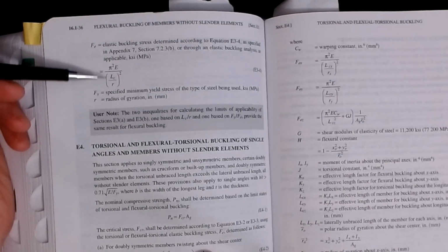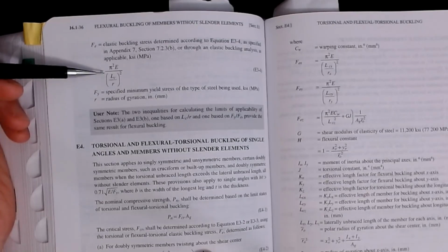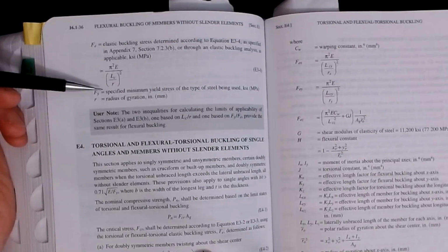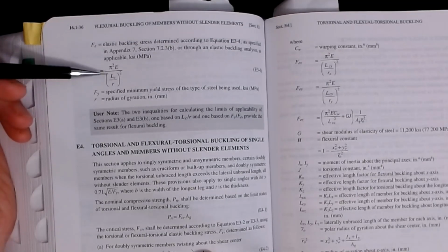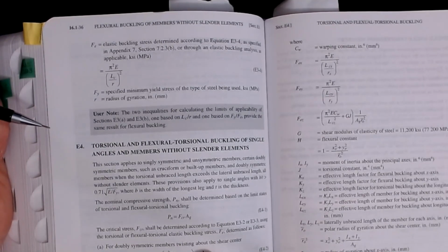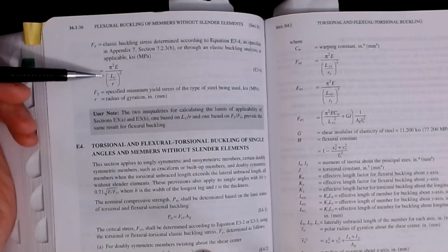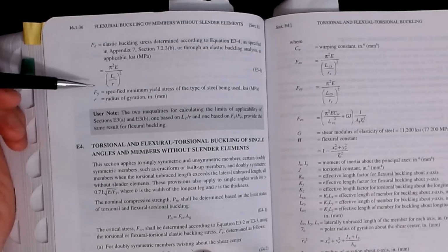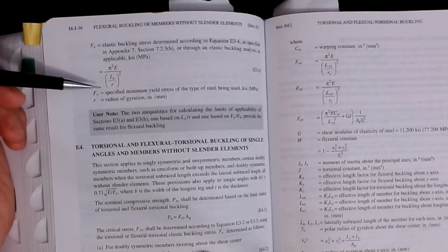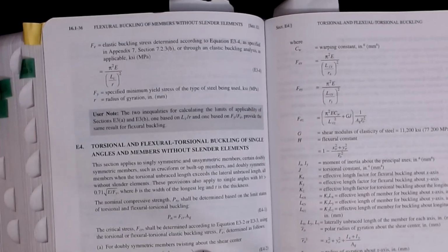So if we decide that we have a different scenario, as we talked about in the last video, where maybe it's fixed, or it's got a little bit of rotation, but it's not truly free, we'll need to include a K in this equation. So everything we do with columns is a KL over R. Whenever you see L over R, just mentally make a note that it should be KL over R to account for that in columns. And then we'll show you what we can do with those formulas as well.